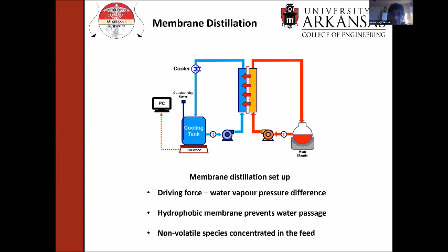Now, commercially available hydrophobic membranes today, like PVDF and PTFE, unfortunately foul during membrane distillation. And the reason is that the feed not only contains dissolved salts, it also contains polar and non-polar organic compounds, as well as surfactants and what are called low surface tension compounds. So these compounds can adsorb on the membrane, foul the membrane, and eventually lead to wetting and passage of water directly from the feed to the permeate side.